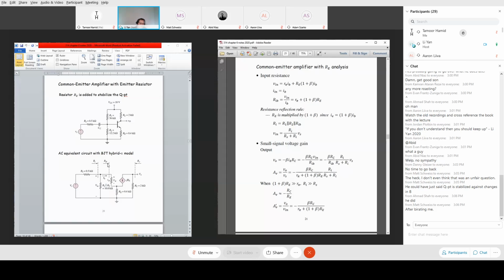Once you find the equivalent resistance viewed at this point, you take one step back. Before this, you have the parallel combination of R1 and R2, which is simply R1 parallel with R2 parallel with R_IB. So you identify the equivalent input resistance right before R1 parallel with R2. Once you figure out this equivalent resistance, you ask how much voltage V_in you can get into this transistor amplifier circuit out of Vs. It is a voltage division relationship. 306 knowledge helps us identify that. That's the purpose of calculating the input resistance: to answer how much voltage V_in I can get out of the source voltage Vs.